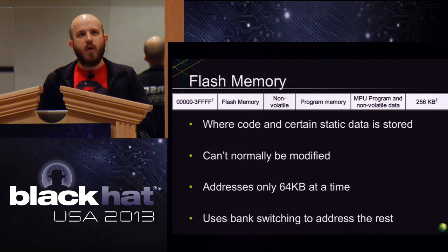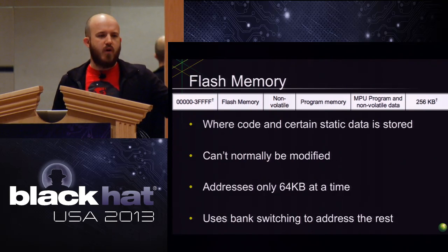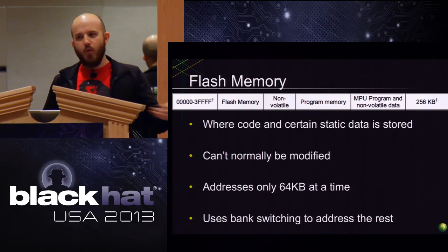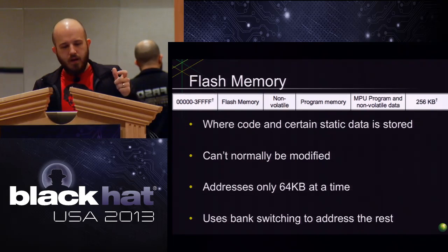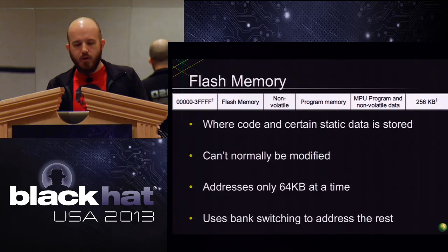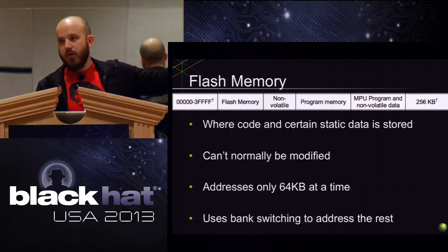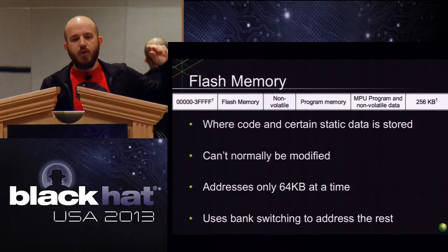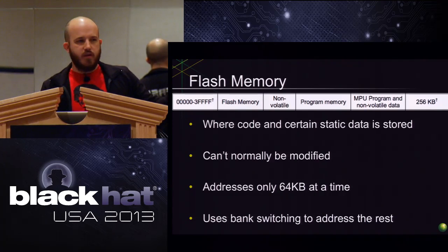So I think one of the biggest things that's stored there in the demo software, for example, is just all of the text, the ASCII that's used for the help thing on one interface. So it's got code and data, but it's never modified data, and the data usually has to be copied somewhere else before you can do anything with it. Flash memory itself can't normally be modified. So true Harvard would mean that this would be read-only all the time. So you would load code with a JTAG or whatever, and then you send the production device out, and then it never gets modified ever.